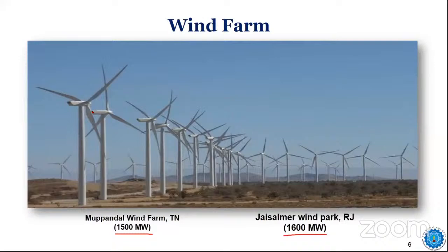If we see, there are these types of wind turbines. These are the horizontal axis wind turbines, which are the most widely employed compared to the vertical axis wind turbines because of the efficiency. Among vertical axis wind turbines, there is the Savonius type and the Darrieus type. There are various types of wind turbines based on configuration and construction. Those Darrieus and Savonius types are generally employed for low power, not for the megawatt range.